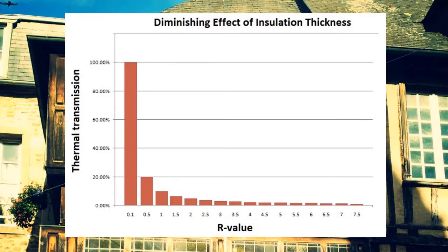Insulation thickness with R value above 4 meter squared Kelvin per watt gives very little additional return on your investment, more so for duct insulation at R3. I don't see the R value stated in the BCA/NCC be increased in the near future.